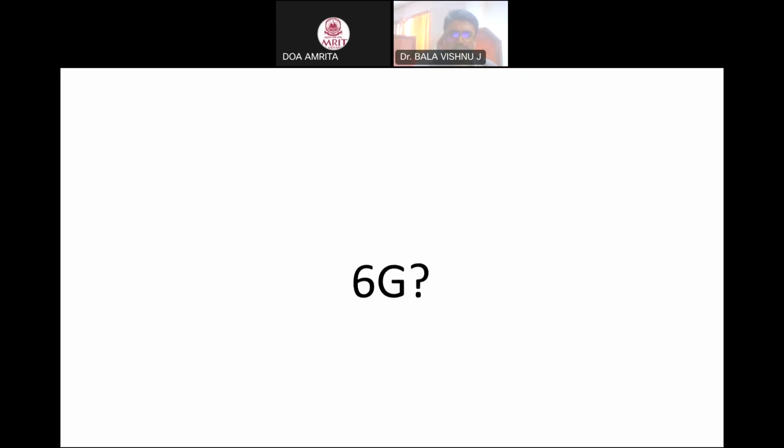So we achieve this by using the intelligent reflective surface in between the transmitter and receiver. Where an obstacle stops very high frequencies in terms of terahertz, the surface receives that signal, also acts as a relay, and transmits it back to the receiver side. So we are combining all this cooperative communication and relaying, and these things together achieve sixth generation communication.